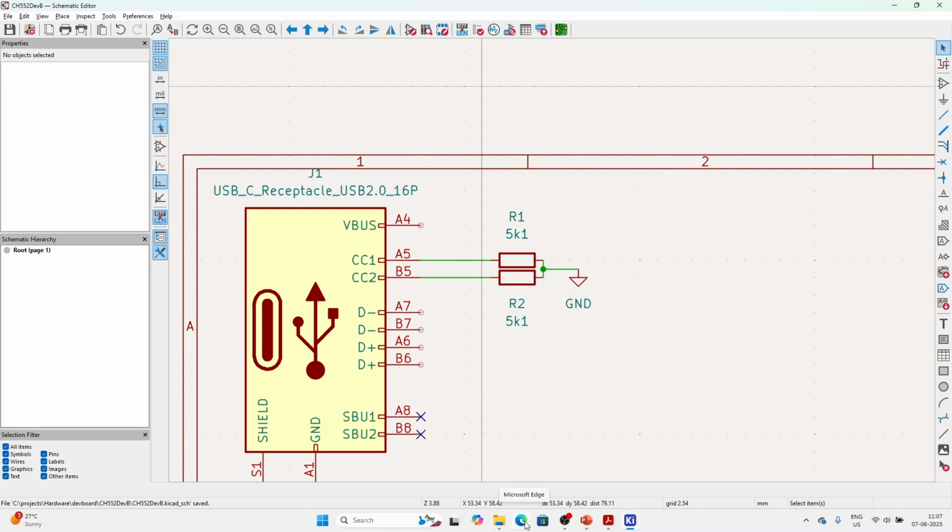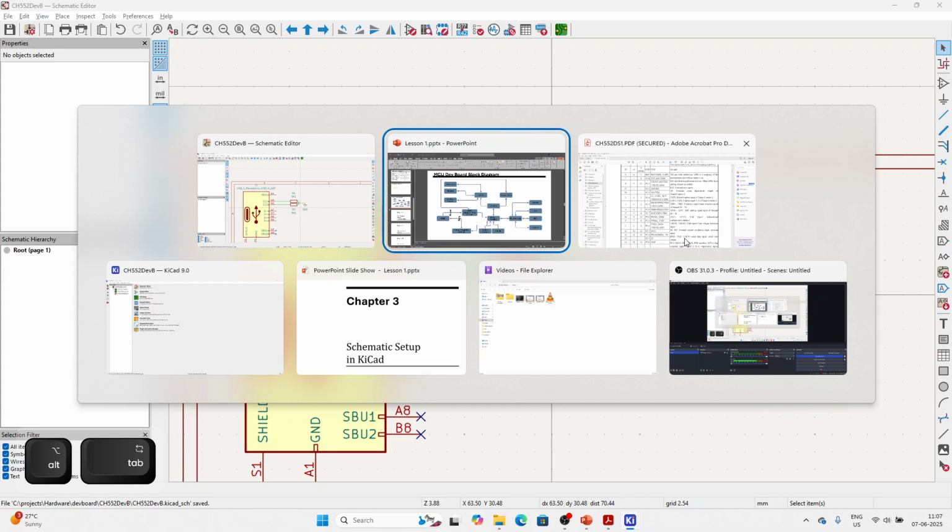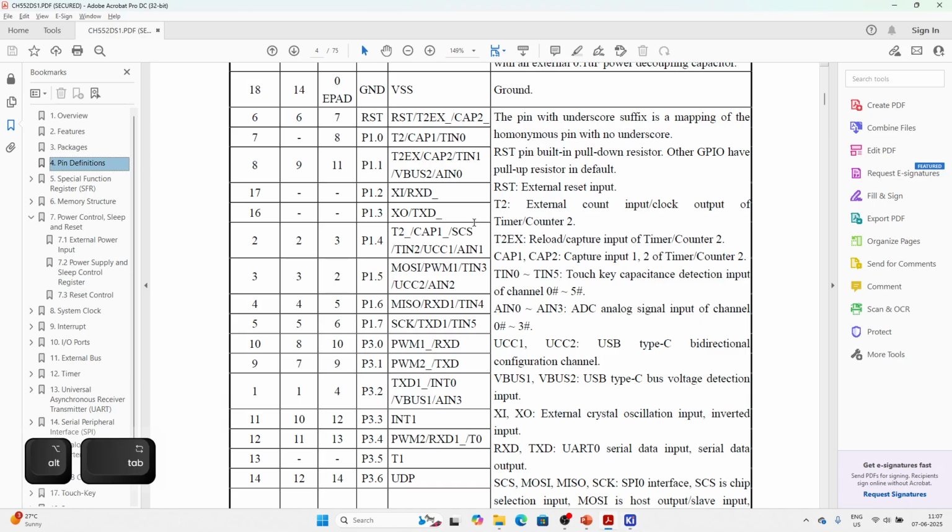power delivery. So let's say I'm using this particular power delivery with PD chargers, then I'll not be just connecting this. I'll be utilizing CC1 and CC2, but those would be very specific scenarios. With respect to this, you see here CC1 and CC2, pin 2 and 3, in order to power negotiate on the VBus.